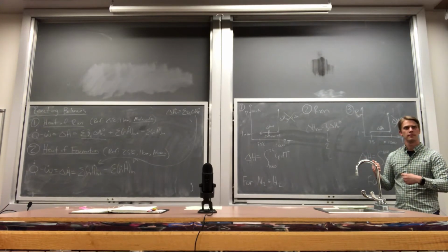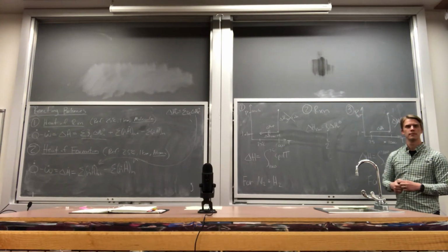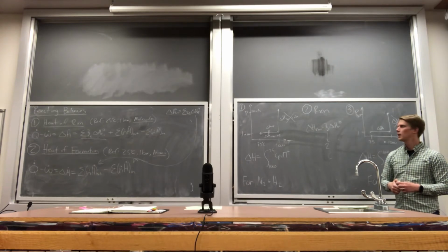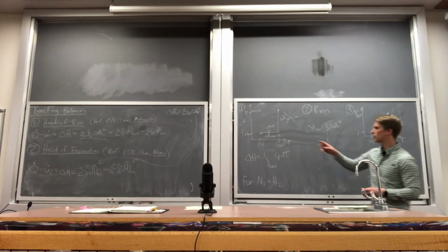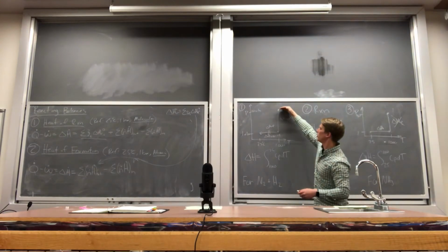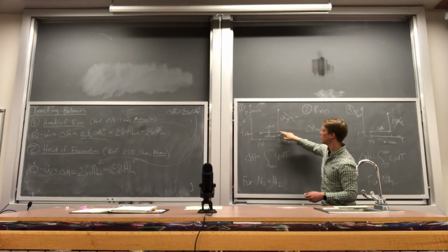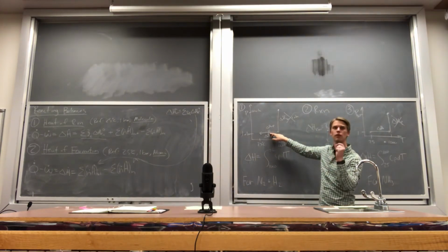Okay. And then, sorry, just to clarify, so then you would start at that boiling temperature, and then you would do the integral of that back down to the reference state, which is 25 degrees? Yes, so let's say in this case we would depressurize the system. Let's say we're a gas at high temperature now. I would cool it down until it becomes a saturated vapor.